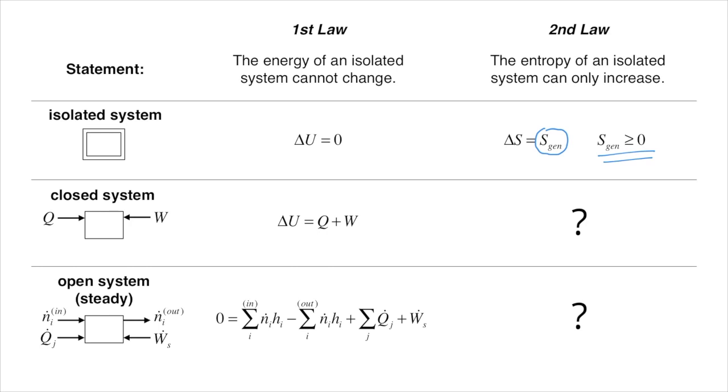So what exactly do we mean by entropy generation? What processes are expected to produce entropy, and what conditions are needed to ensure that it is not generated? We can try to understand entropy generation in a couple of different ways. The first is to consider what happens on a molecular level, specifically how we expect the multiplicity of a system to change when transformed via heat and work.